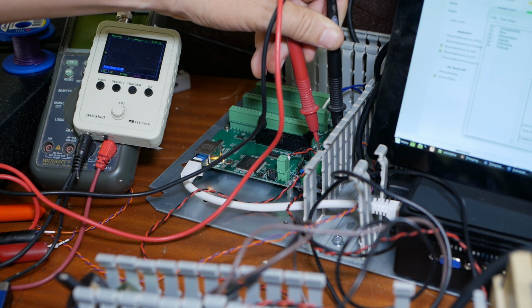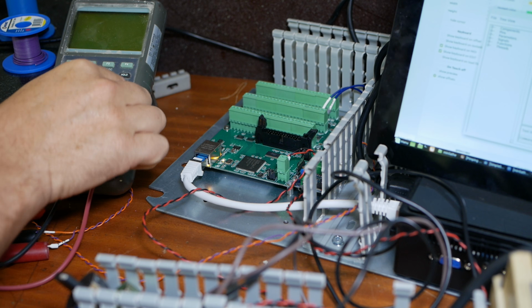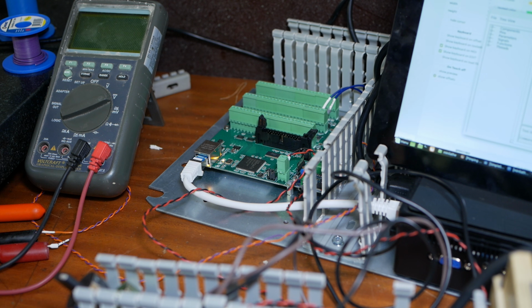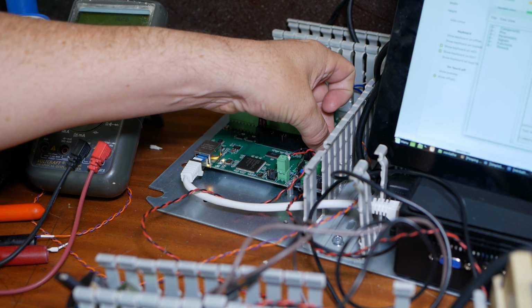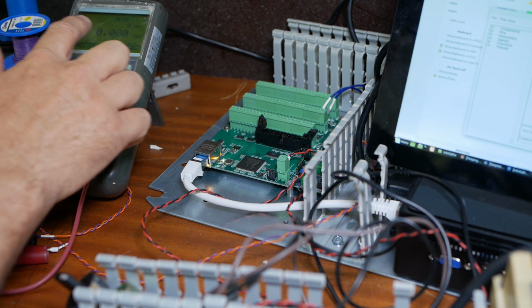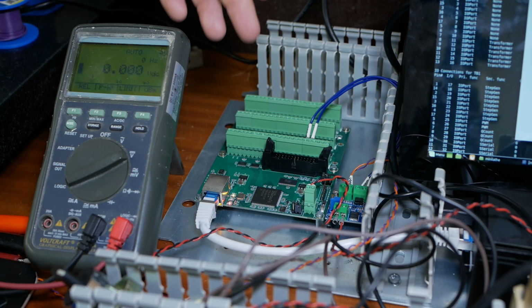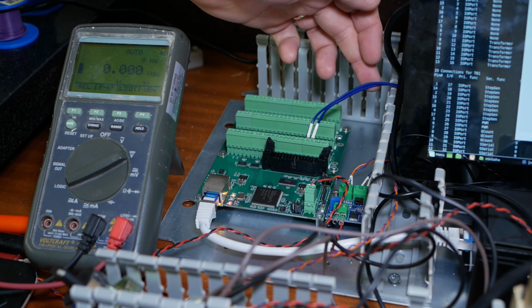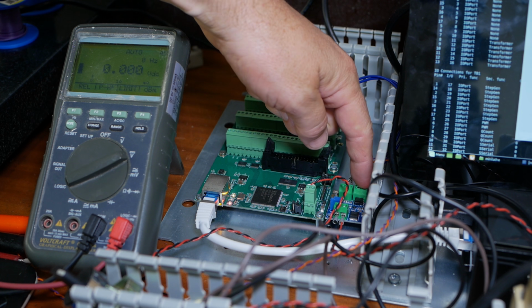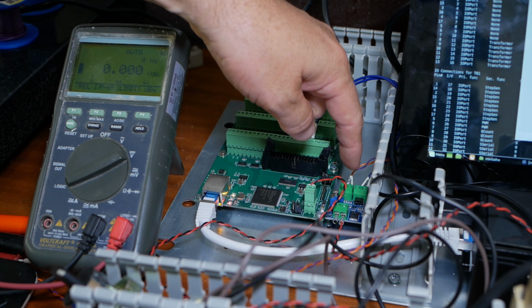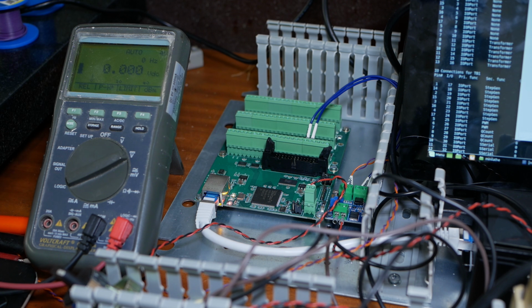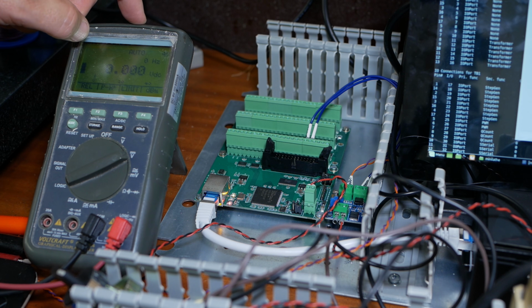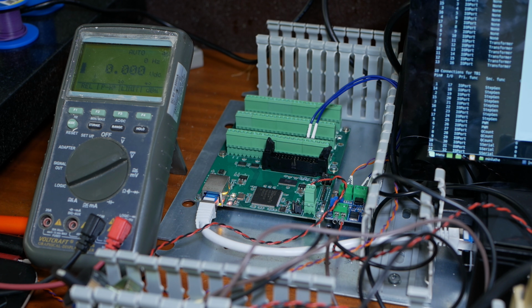That then comes into here, and we should now get DC voltage coming out of these lines. But as you can see, we don't. We've got our signals coming out of here into the board. The board's receiving 19 volts and should send a 0 to 10 volt DC signal down this line, which I've connected to the multimeter. So hopefully I can now get some voltage control.